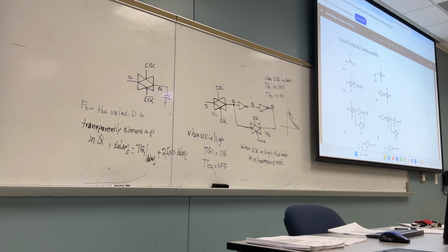Clear? Did you get it? Yes. Oh. What is, again, one more time. What is the delay between the D and the Q? The delay between the Q and the D is what? Delay of TG1, yes? Plus what? The inverter. You follow me or not?